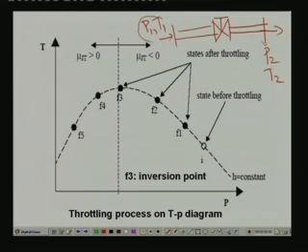To start with, I keep the pressure and temperature at the inlet constant. Once you fix the pressure and temperature of the gas at the inlet as constant, the enthalpy is also fixed. Let's say that enthalpy is this. So the enthalpy at the inlet to the throttling device, which is nothing but the valve here, is fixed. Since this is an isenthalpic process, the exit enthalpy is also fixed, and that is nothing but the inlet enthalpy. H1 is equal to H2. So I close the valve to a certain position, and I measure the exit pressure and temperature, and I put one point on the temperature-pressure chart.